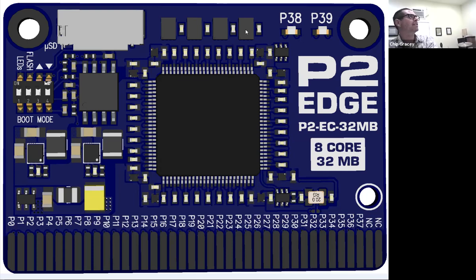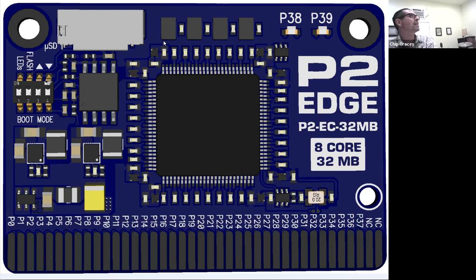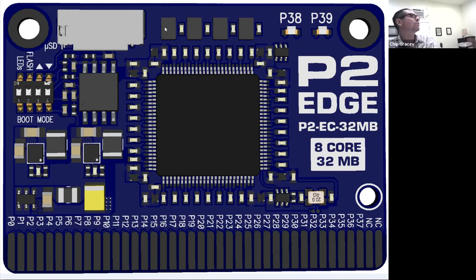They're kind of like QFNs, 2x3mm each. The pins are around the edge, but underneath, like you can see them hanging out the bottom here. It only has pins on the top and bottom of each, and not on the sides. There's 4 across the top, 4 across the bottom, and then a little tiny sliver across the middle, which is ground. So it's like an SO8, but reformatted to be real small.